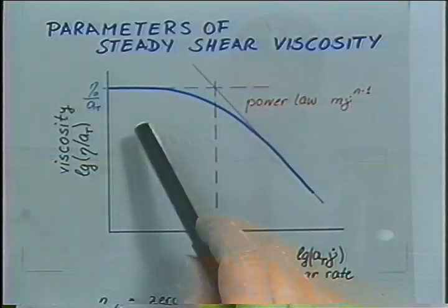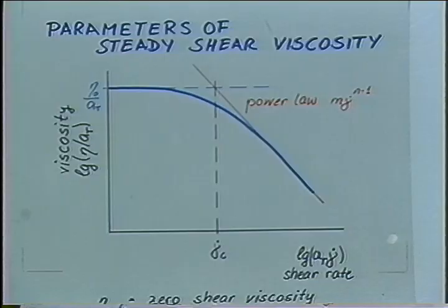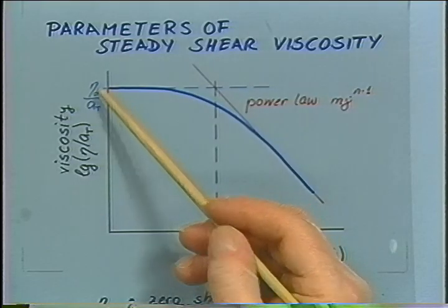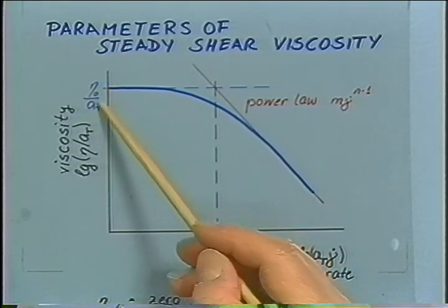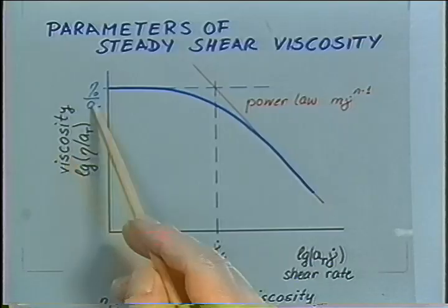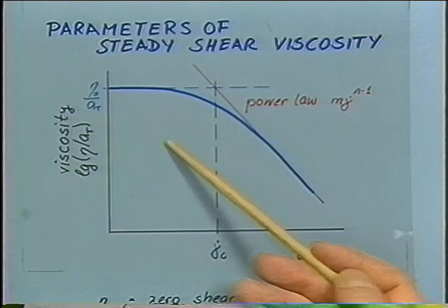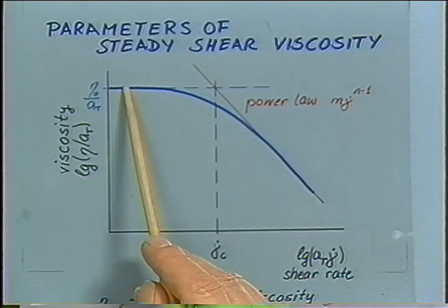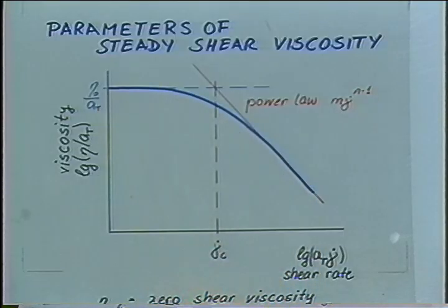Or we could plot all the results in terms of just one viscosity function, where we divide the viscosity by the shifting and multiply the shear rate with the shifting. In the log-log scale, this is equivalent to the shifting under 45 degrees. And we note that just one shape of this curve is found.